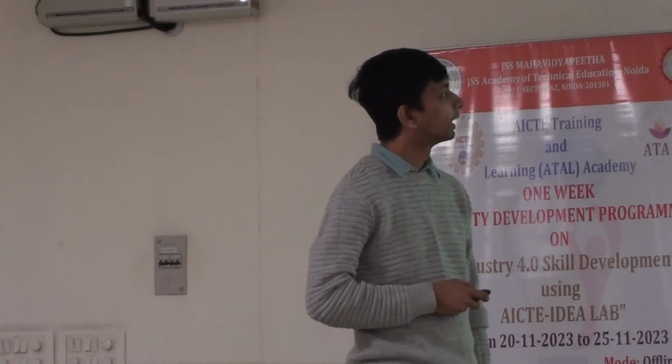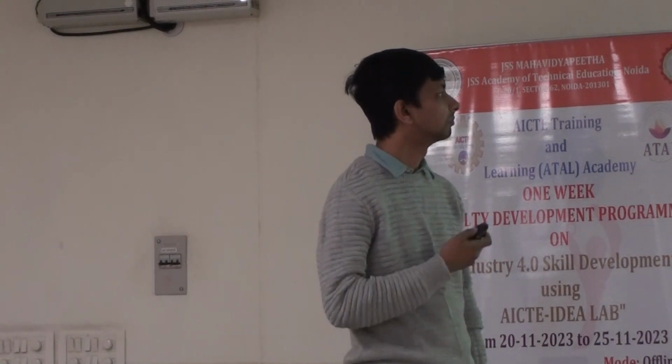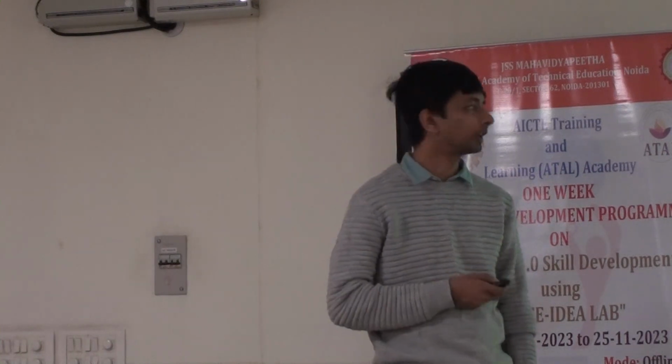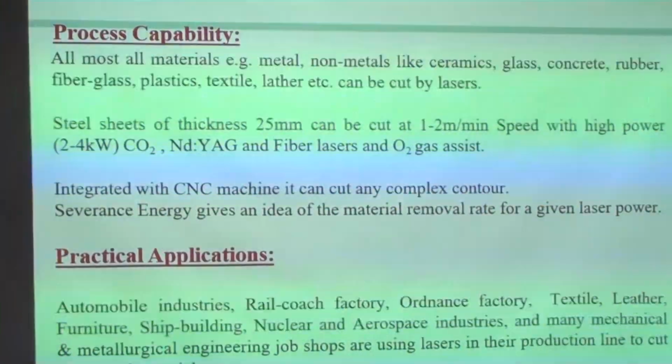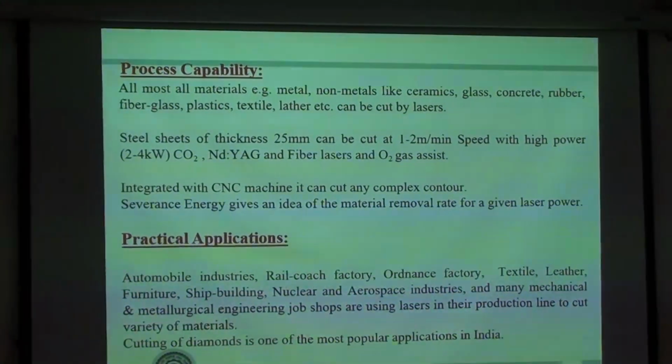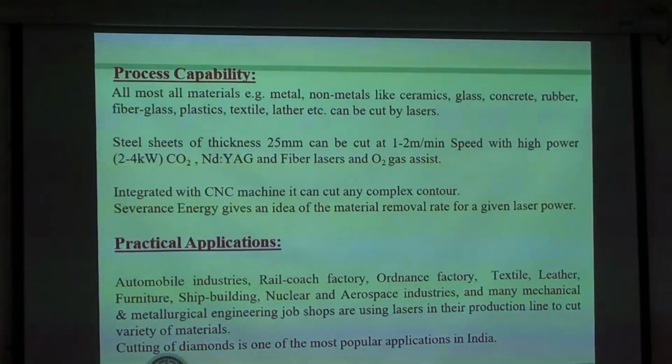It can also cut textiles, leather, and perspex sheet. Almost anything can be cut with high precision. Cutting thickness can be as high as 60 mm, which we have already demonstrated, and there are different alternatives. Depending on the application, you can select the right laser system, but predominantly the fiber laser and the CO2 laser are being used at this moment.